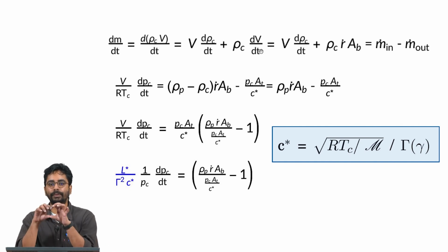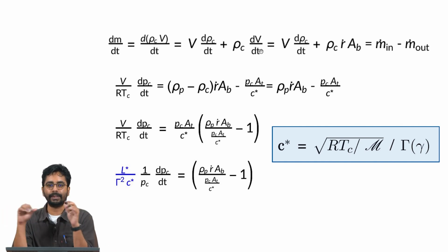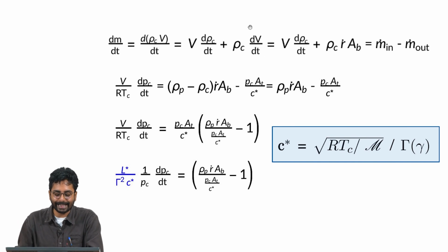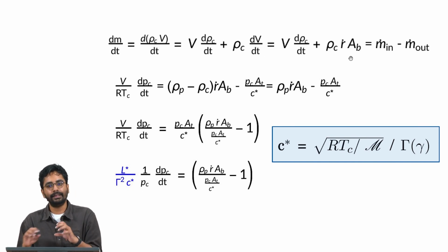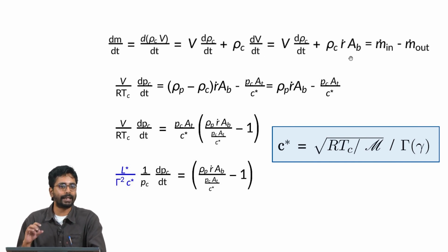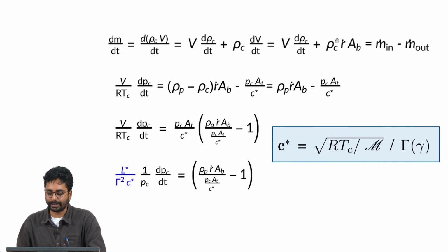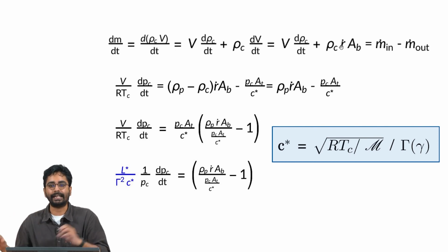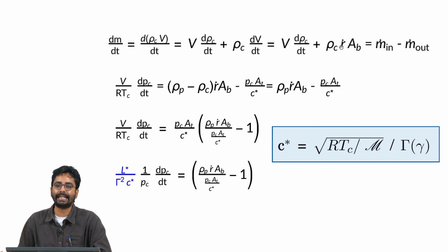See, you start with a certain volume inside the port, and as the propellant burns, that volume will increase, right. That increase in volume is nothing but the volume created by the conversion of the solid propellant into gases. This is nothing but the rate of burning of the propellant multiplied by the burning area of the propellant, okay, that is the increase in volume.